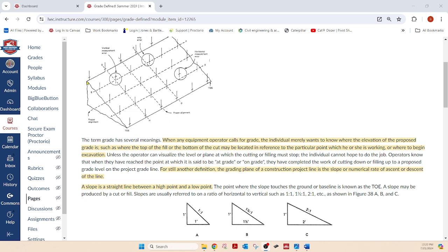It could vary. If it's 20 feet up in the air, and this is 40 feet deep right here, we're going to have us a 2 to 1 slope, by golly, because it's 20 feet, or yeah, 2 to 1, because it's 2 feet like here, 2 and up 1, 2 and up 1, 2 and up 1. So we'll have a 2 to 1 slope here. That would be, if it's 20 feet high and it's 2 to 1, it has to be 40 feet deep.